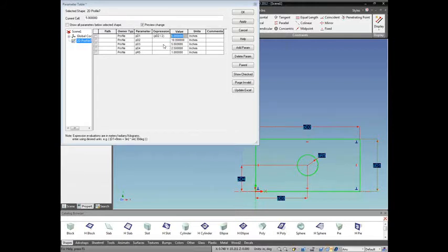And let's see, this one also will be, so the circle is always halfway along the length. Put in that PD2 divided by 2. This one will be half the width, so it'll be PD1 divided by 2. And then the radius, I always want it to be 1/5 of the width, so I'll put in PD1.